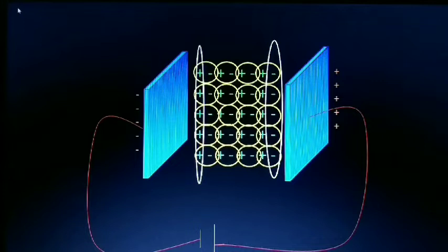Therefore, negative charges will be accumulated closer to the positively charged capacitor plate and positive charges are accumulated closer to the negatively charged plate. As a result, the dielectric material now is acting as a polarized material, having a negative pole on the positively charged plate side and a positively charged end on the negatively charged capacitor plate.